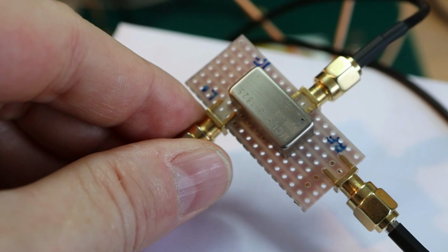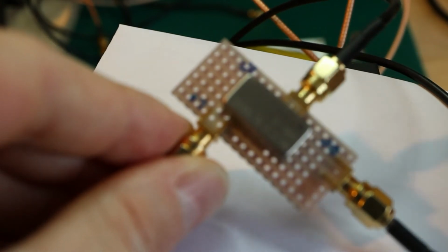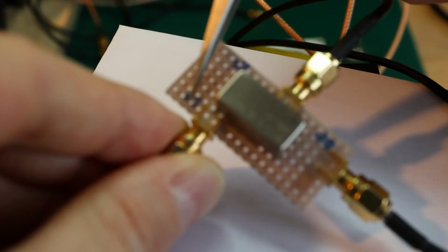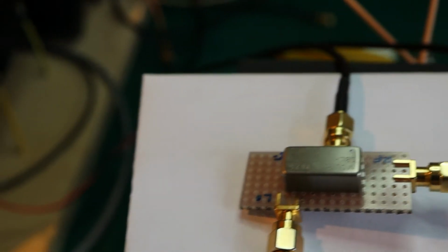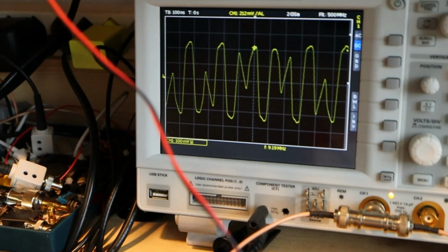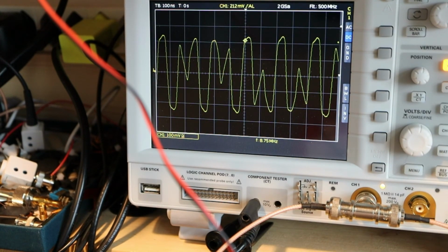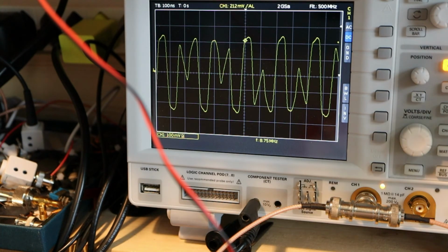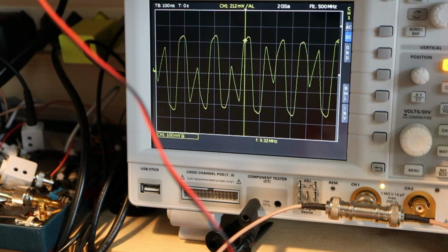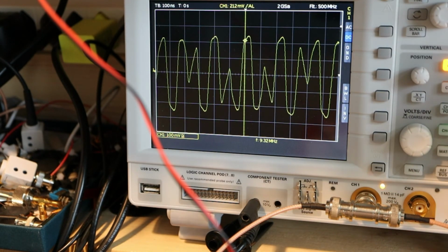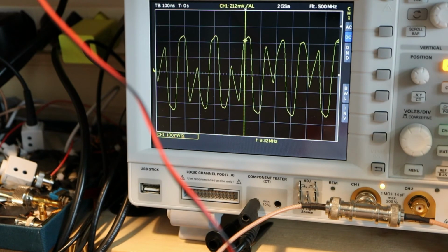What we have here is the RF input, the LO input. I have a 7 megahertz RF input here, a 2 megahertz LO sinusoidal input here, and this is the intermediate frequency that we want to measure. And you can see here on the scope, that's the intermediate frequency, the output. I have 1 volt peak each signal for RF and LO, and this is the output. And you see that's pretty much what we have seen on the SPICE simulation as well. You can see the main 7 megahertz signal, which is clocked and chopped with the 2 megahertz LO frequency.